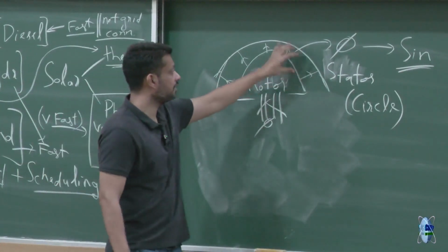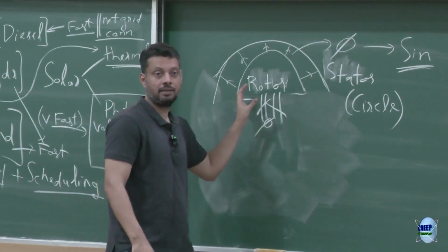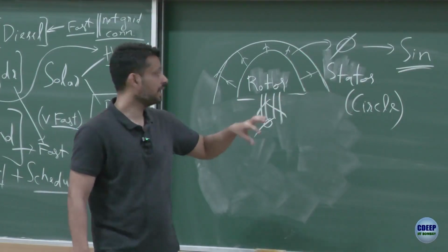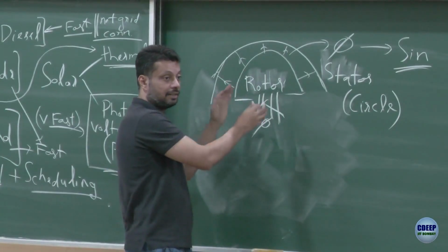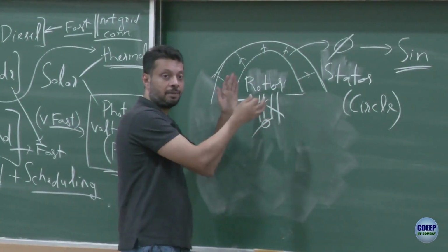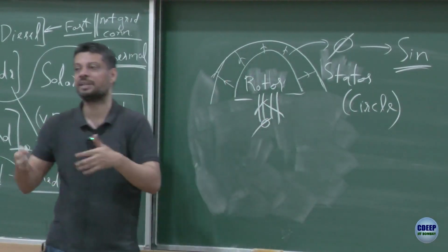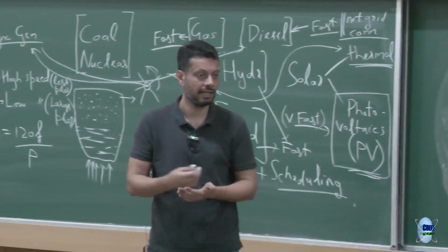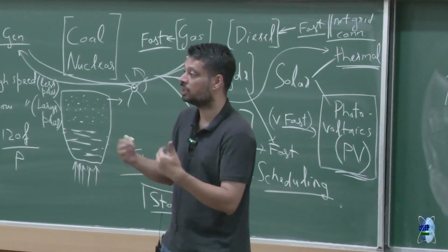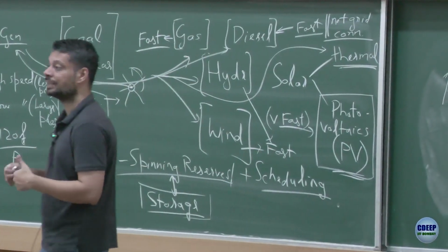Earlier you had a constant flux density, so if you rotated it, you got that kind of wave shape. Now you have sinusoidal flux density. So if you rotate it, you do E equals N d phi by dt, and the derivative of that sinusoid or cosine would eventually lead you to a sine or a cosine. So the shape of the voltage induced is now going to be sinusoidal.